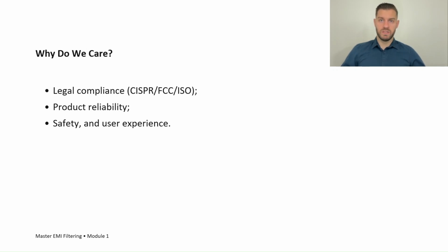So why do we really care about EMI? Well, first of all, it's for safety and for user experience. And we'll see what that means in real life in later slides. But for now, let's just say that there are standards that govern EMI, and those standards basically say how much EMI your electronic equipment is allowed to emit to nearby sources or back onto the grid. Some of these standards are CISPR, FCC, or ISO.